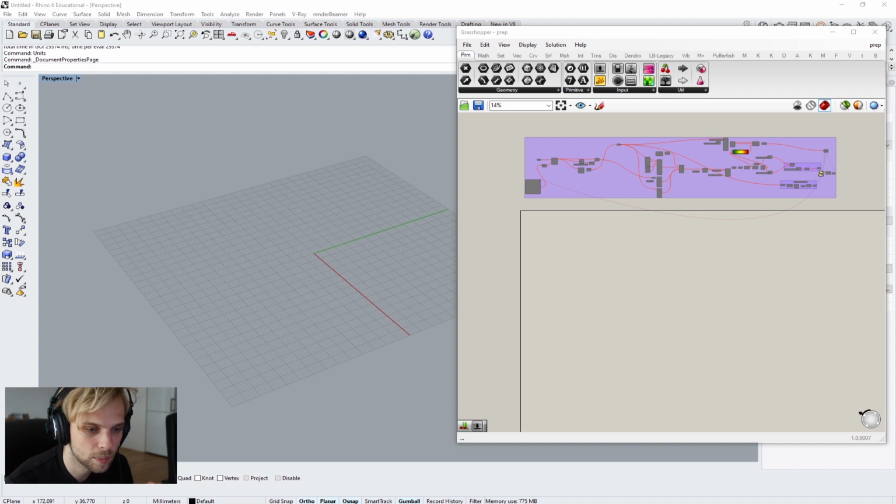So it can optimize the amount of beams versus the average length of all of those beams, right? So you have two variables. With Galapagos, you can only do one or the other. It just basically takes one number and increases or decreases it. Octopus can take multiple numbers, right? So that's why it's multidimensional.